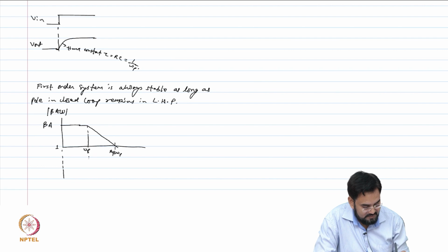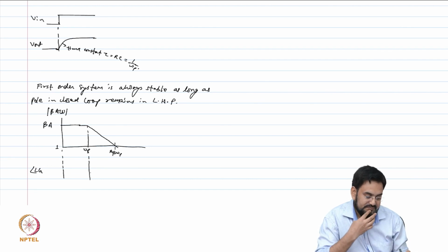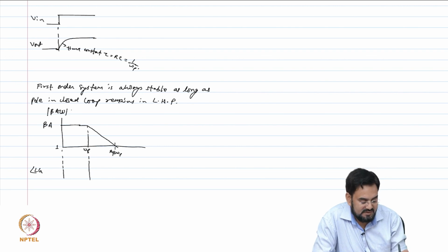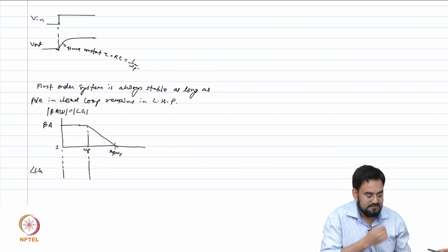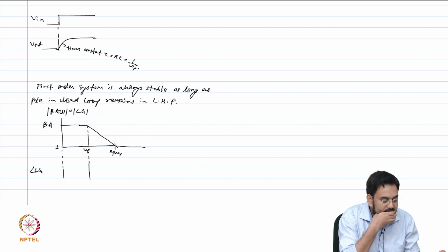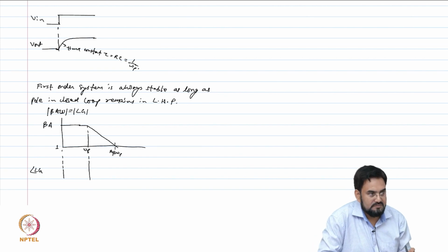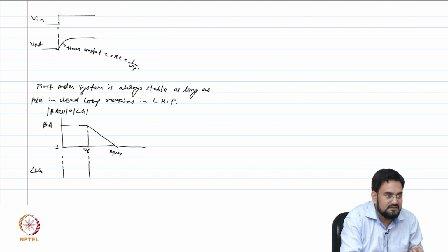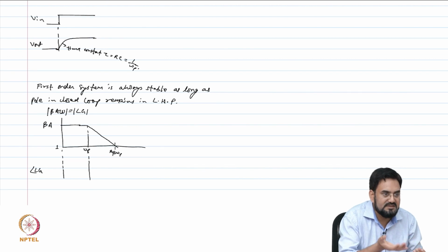This is one. So how do you draw the phase of this, your loop gain? So this is nothing but your loop gain. So where will it start from? 0? So negative feedback, huh? So 180 is already there. 180 phase shift is already there even at a 0 frequency or DC. So you have to start with 180, you cannot start with 0.